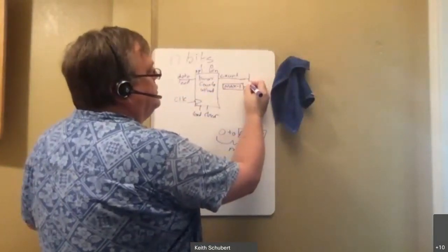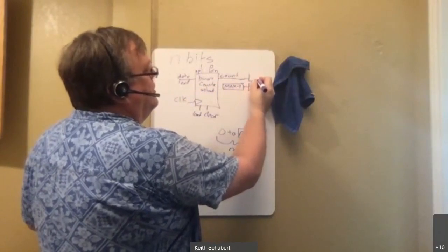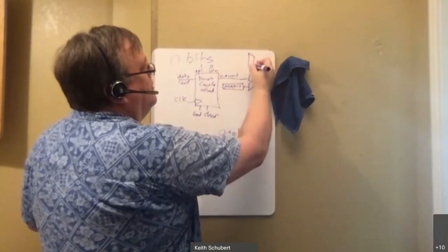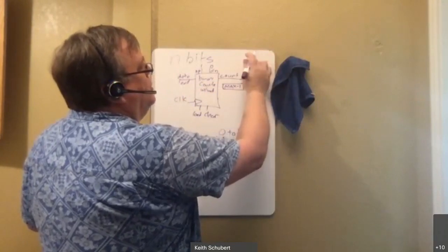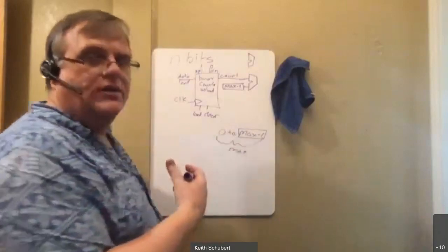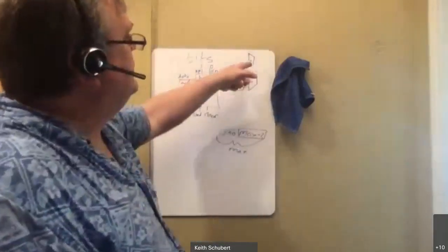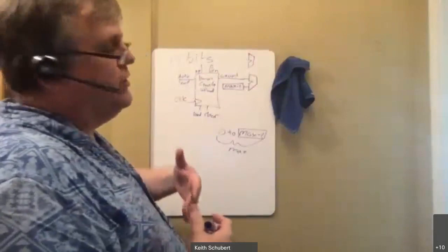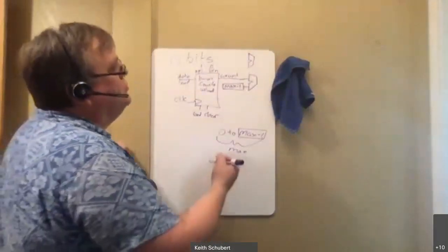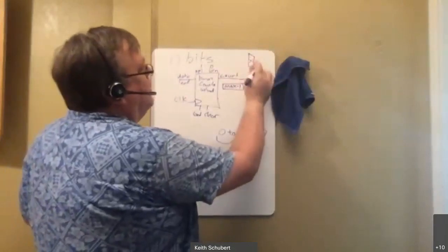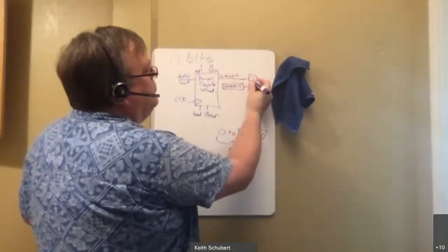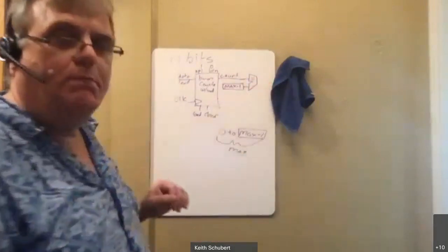And there's a couple of ways. This symbol right here looks kind of like your mux shape, but then I pull a notch out of it. That's an arithmetic logic unit. So what that means is it could be a general ALU or it could be a very specific thing. There's two different ones I could use here. Let me give you one type and then we'll talk about the other. I could do just what's called a comparator.